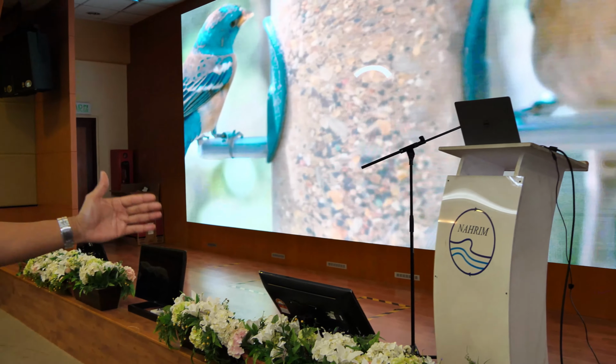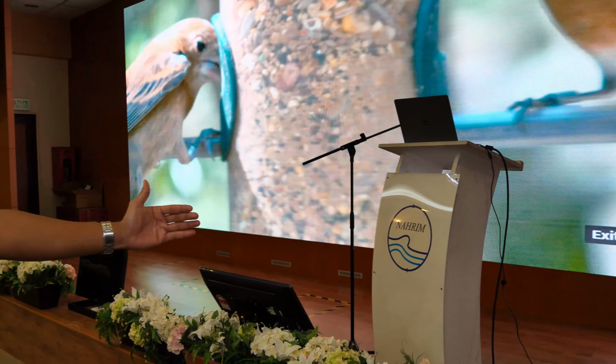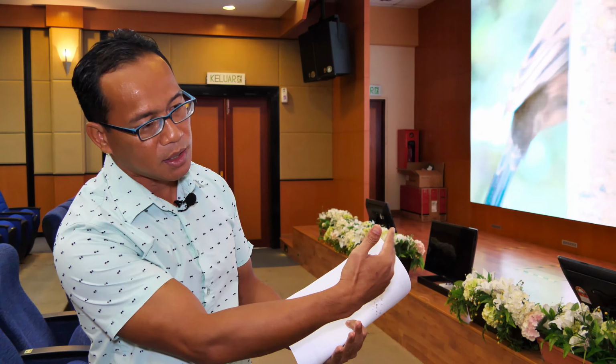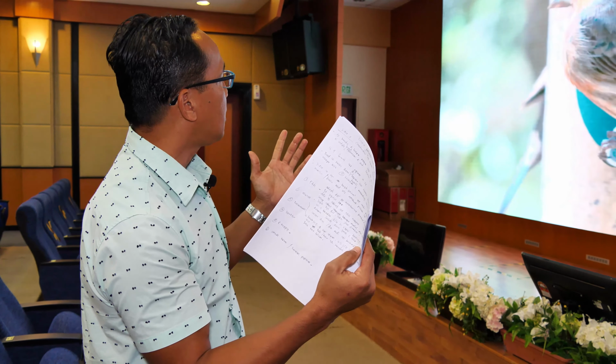For example, if the distance is about 5 or 6 meters, this is the front row. When I'm standing here, looking at the screen, I barely can see the pitch or the dot. That is how you determine the quality, because you don't want to look at the screen and see a big dot. Here, using P2.5 and standing 5 or 6 meters from the screen, I can appreciate the quality of the video. So that's how we determine 2.5.